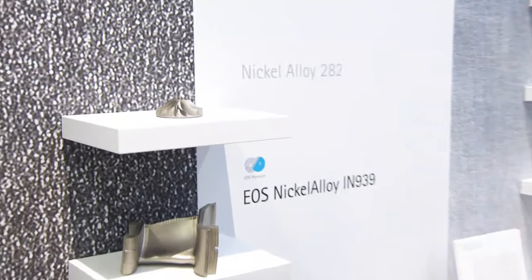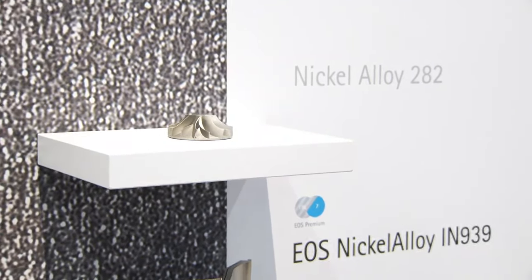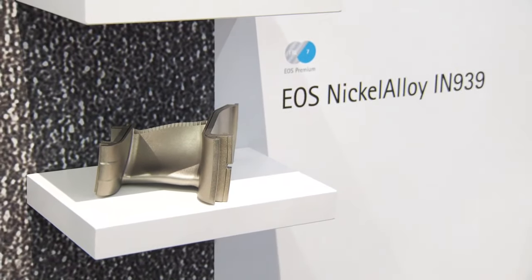So also on nickel-based alloys, we have some news. We have Inconel 939 and the 282, which is popular in North America. They are even more heat resistant than the well-known Inconels 718 and 625 we already used to have in our portfolio. People love the Inconels, and even 939 is totally new. Maybe it was hard to weld, but we managed to have now an Inconel 939 on the market. This is incredible, and people love this material, also because of its high stiffness and strength in the high temperature range.